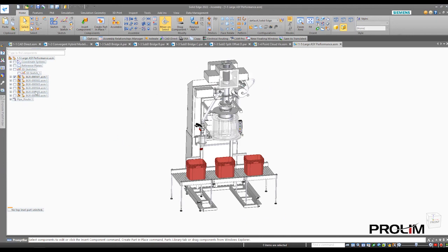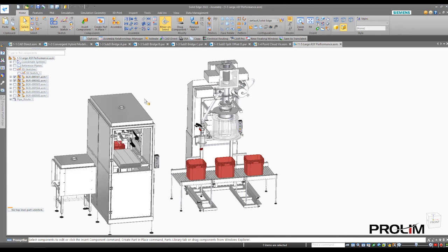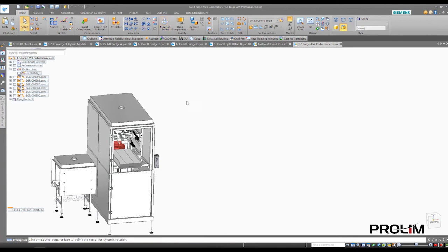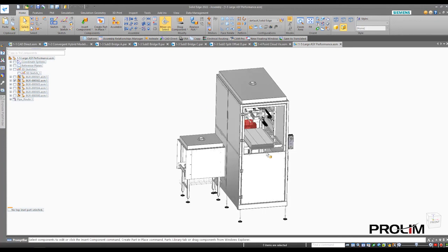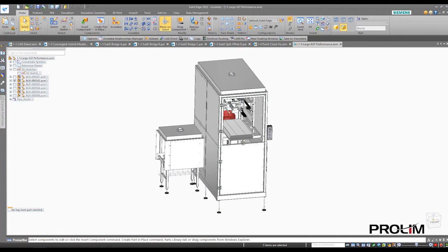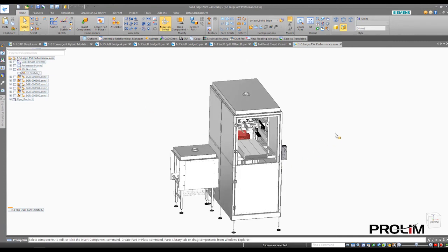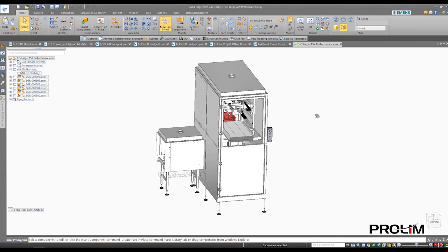So if I wanted to show, now I'm off of that one and I'm into this one. Now when I save this file and I go back into that preview mode, if I have Last Save selected, when I go to open to make the edits, this is going to be the configuration that opens. So again, this is a combination of using the configurations together with some other things.